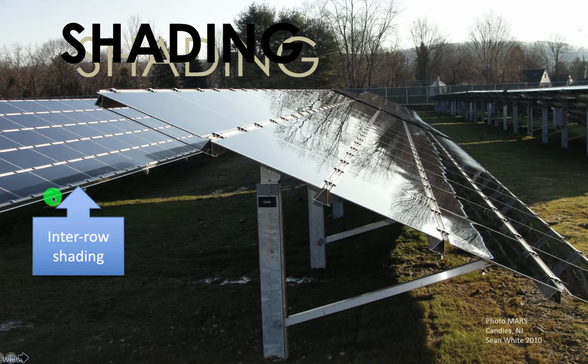Perhaps they didn't do that because it was an engineering decision, and the engineers decided that they could do with those winter morning losses. They might not have had enough real estate to fit everything if they spread the rows further apart, and if they tilted it less, then they would have lost more production for not being tilted at the sun as much.